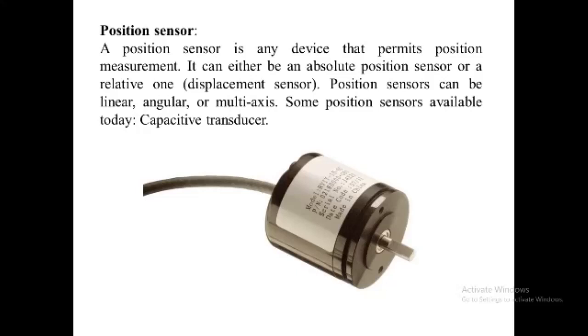Generally, the optical disk used in a rotary position encoder is circular. Then the resolution of the output will be given as theta equals 360 divided by n, where n equals the number of segments on the coded disk. For example, the number of segments required to give an incremental encoder a resolution of 1 degree: 1 degree equals 360 divided by n, and therefore n equals 360.